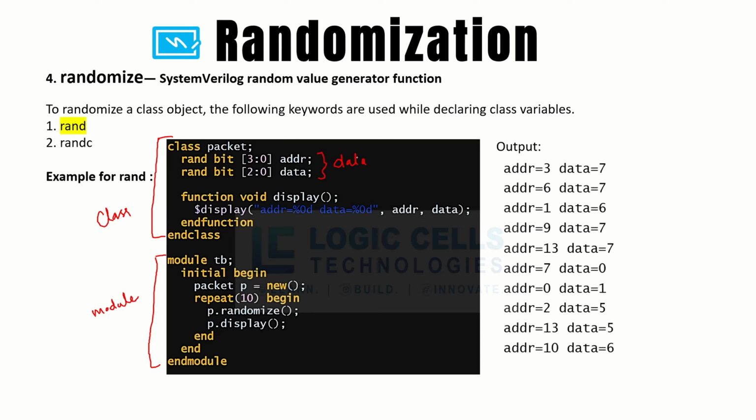What exactly a class consists of here in our testbench: we will be having the data members. Data members directly refer to variables, what we have declared. Variables inside a module, we will be declaring A and B, right? In your adder case, those A and B can be written inside a class now. If you put it under a class, you can observe inside a module, this packet class is called here. You can see packet, correct? Here we have packet, and we are giving a name of that packet inside my testbench, P. Now we will be accessing this address and data through P.